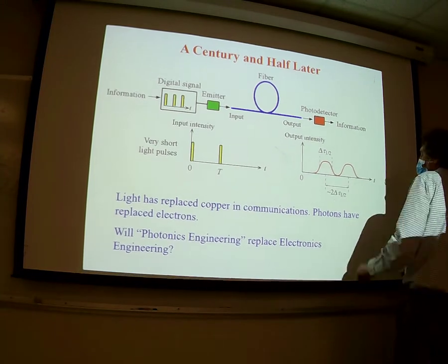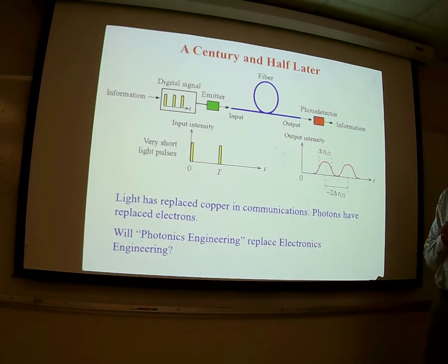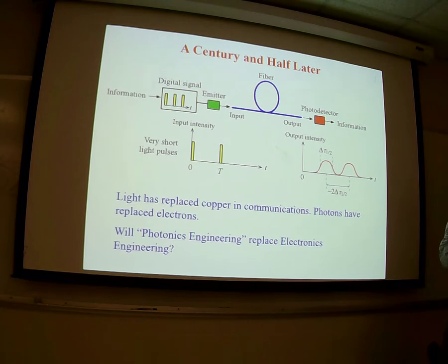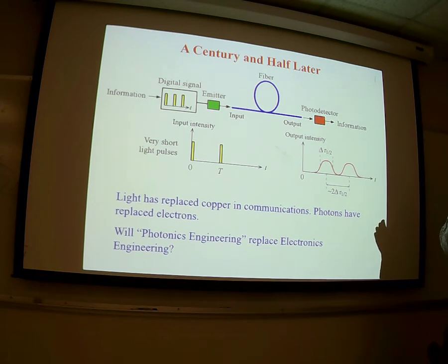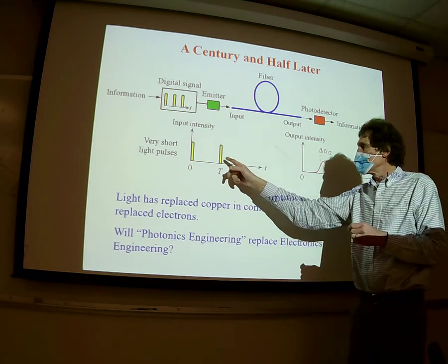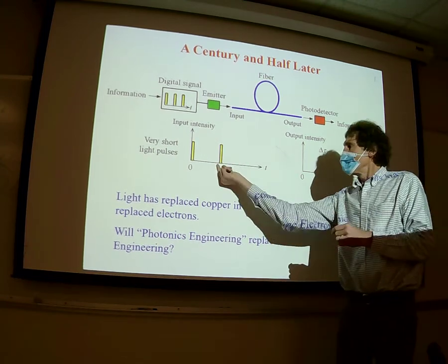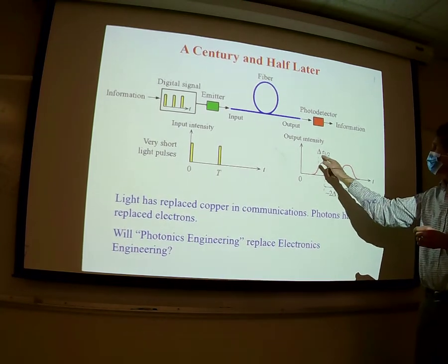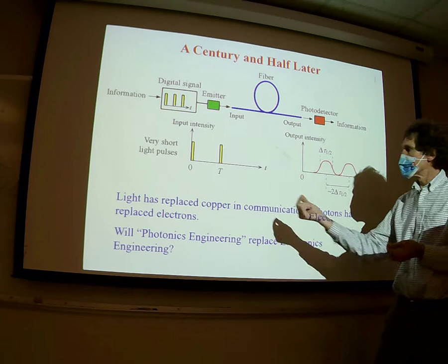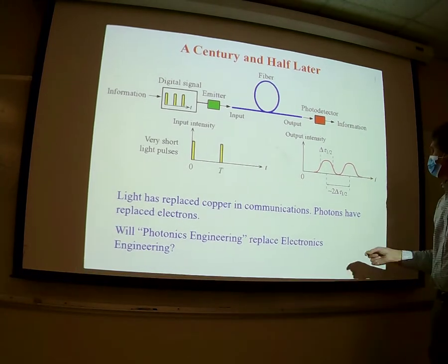So anyway, coming out here, you don't get something from nothing. Part of this is due to what's called the rise time on any kind of photodetector. Y'all realize that all real things that detect changes have a limit to how fast their output can change. You can't go from no voltage to 10 volts instantly. There's a finite time, rise time. There's also something that as this moves through, these would represent packets of light. They'll be broadening too. So what comes out of a photodetector is something like this, where there's a delta tau associated with that, and then there's a space in between them.